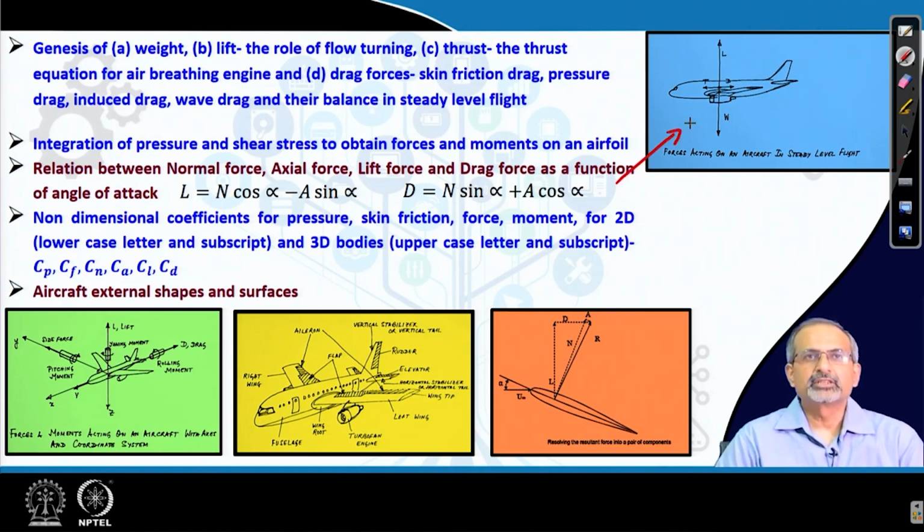We learnt about integration of pressure and shear stresses to obtain forces and moments which act on the airfoil. And then we looked at the relation between normal force, axial force, lift force and drag force as a function of angle of attack alpha. So, we recall these very important equations connecting the forces.